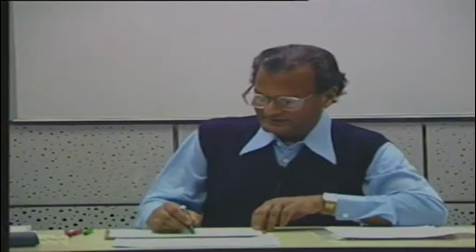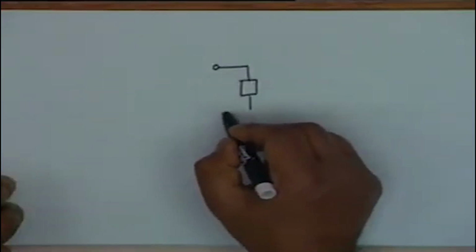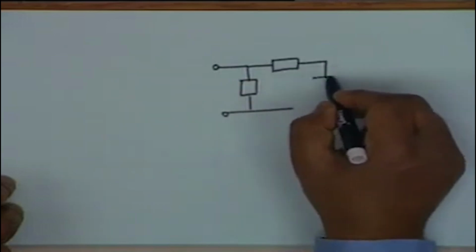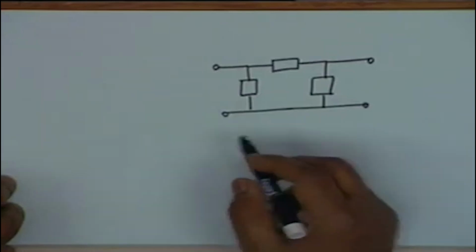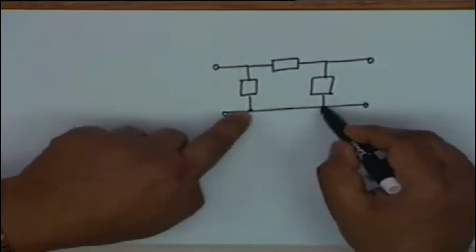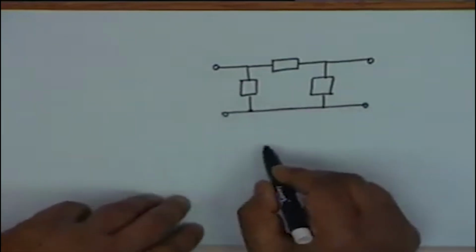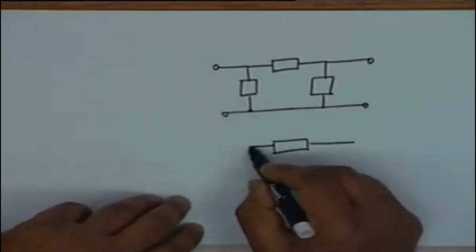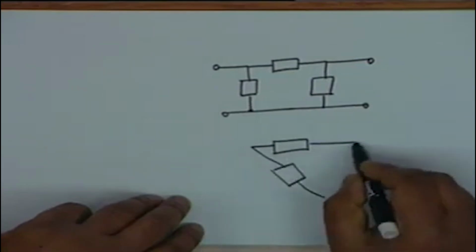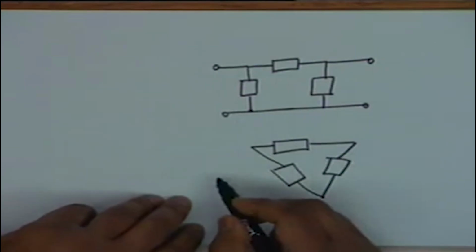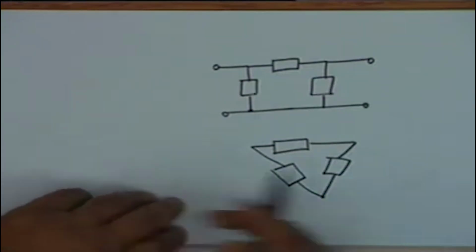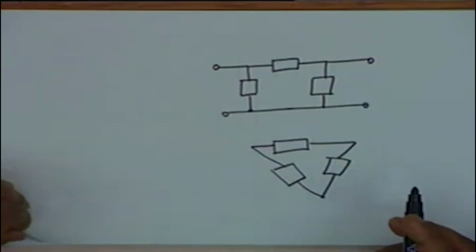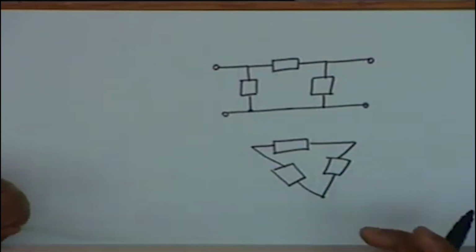This pi network which we have just drawn is the short circuit Y parameter equivalent model of the equations. Well, if you pull these two terminals close together, then another way of representing this network is a delta. This looks like a delta, and therefore this is also called the delta network model. Instead of pi, it's also called a delta network model of the two simultaneous equations.